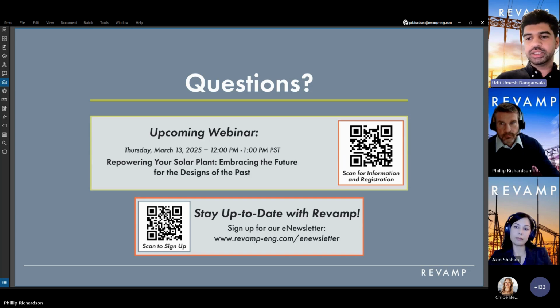The question is, in harmonic studies, how do you handle the Norton equivalent impedance of the inverter and things like frequency dependency of cable impedances and capacitance of transformer windings? That's a really good question. Some software like ETAP does not allow that level of modeling. However, more sophisticated software like PSCAD can be utilized. For greater accuracy, these elements can be modeled in PSCAD as capacitances and inductors rather than just reactances. That way the frequency dependency can be accounted for.